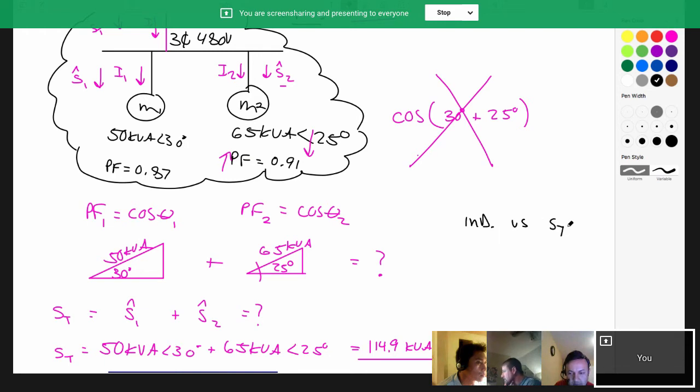The conversion mechanism. Yeah. Synchronous motors, you've got an excited rotor, don't you? If you overexcite that rotor, it's going to operate as a leading machine. If you underexcite that rotor, it's going to operate as a lagging machine. How about an induction motor? Can we run power factor control? No.